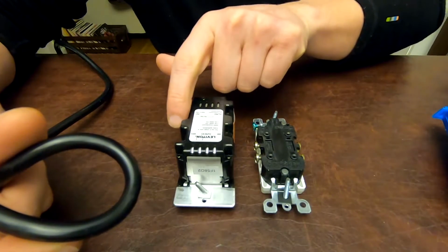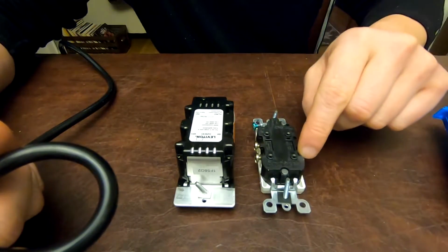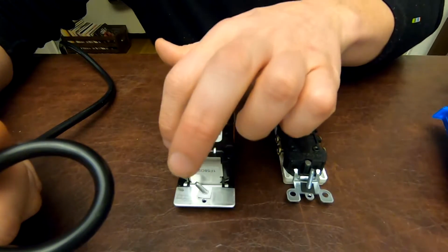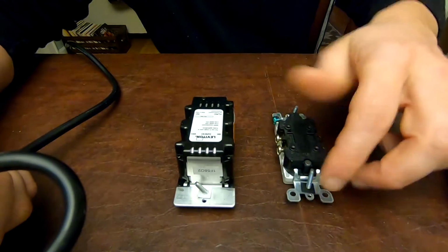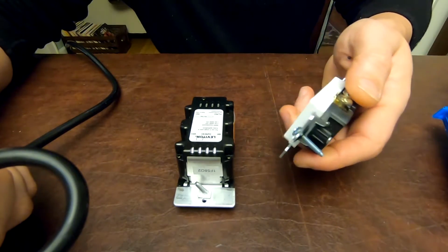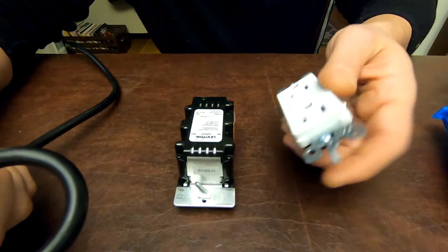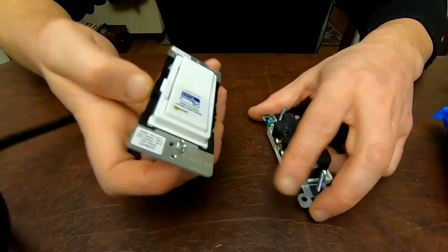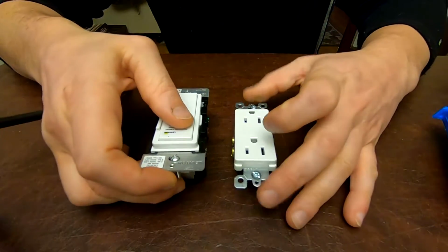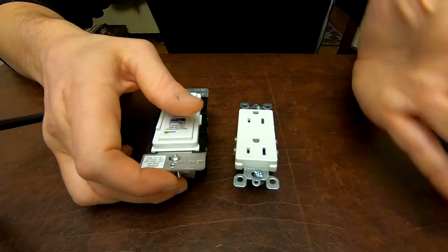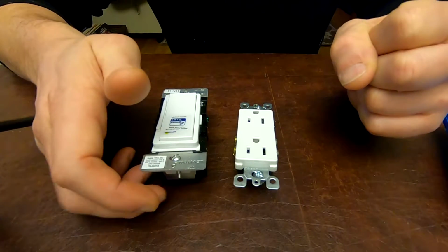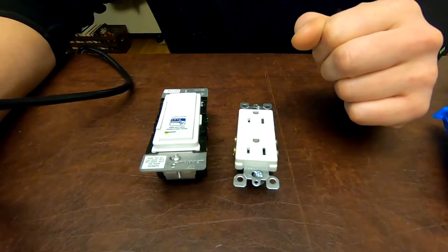The load is going to be a separate lead jumping over to the positive on your outlet. The white is going to come right off of the neutral here and jump off of there to the silver screw to neutral on the outlet. And then essentially what we'll have is a dimmer controlling an outlet that controls a transformer that controls the light level of my under cabinet lighting. I think that sounded pretty good.